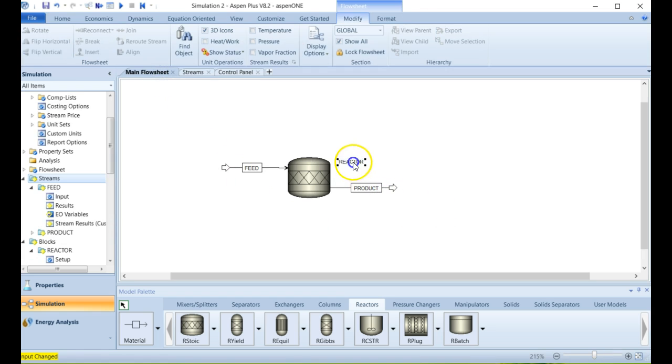Now, it's very common in reactors, when they achieve a specific extent of reaction, that you'll always have some of the feed reactants coming out in the product. And oftentimes, you'd like to actually recycle those. If you can purify them somehow and send them back into the reactor, we can get improved yields. And the question is, what would it look like in our reaction to do that? What would happen to our energy requirements? What would happen to the sizing of the reactor? And all these other things that we would need to know.